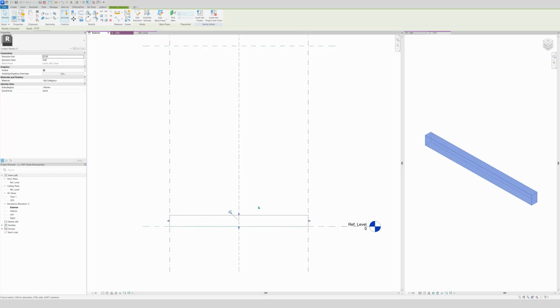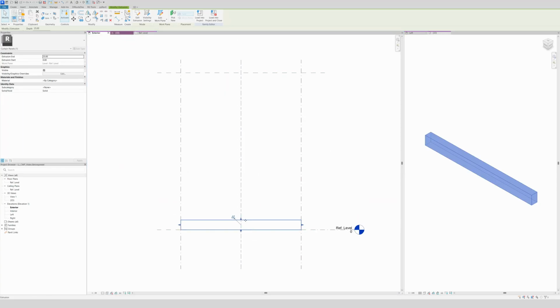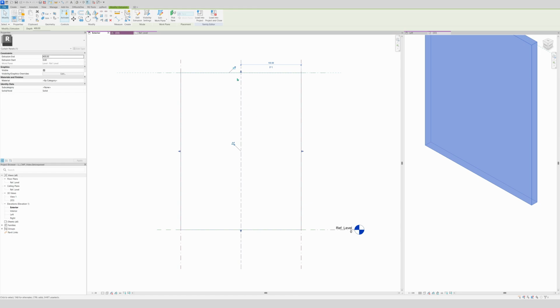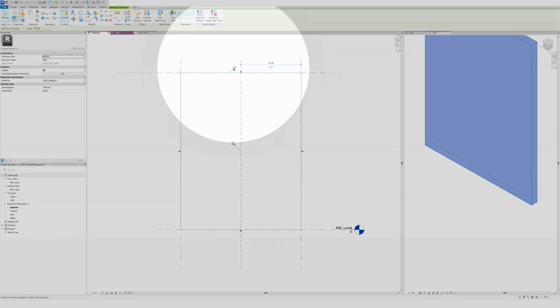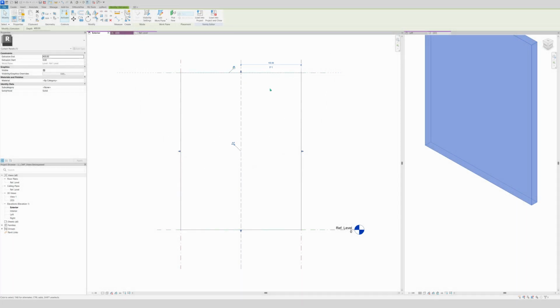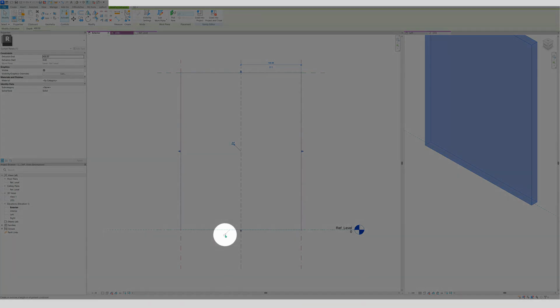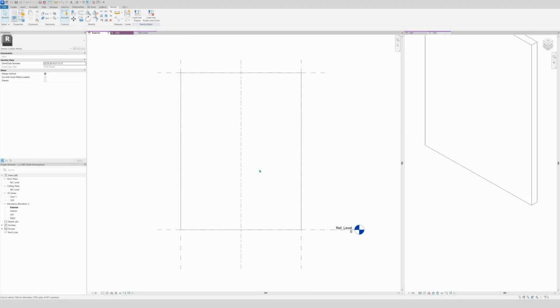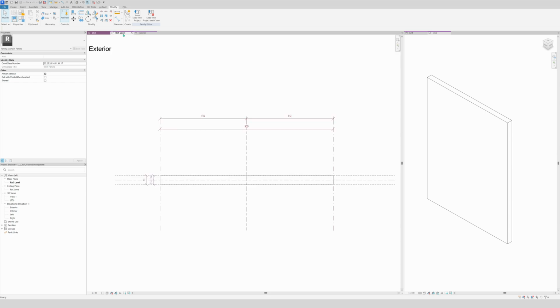Voila. So we have our generic extrusion, but we'll need to lock it to the top of it, and it will automatically snap, as you see. Then be sure you lock this icon. For the bottom also, you just move it upwards and then it will automatically snap, and then again make sure you lock it, and voila, that's it for now, of course. And now you see I will move this to right here and this to here.